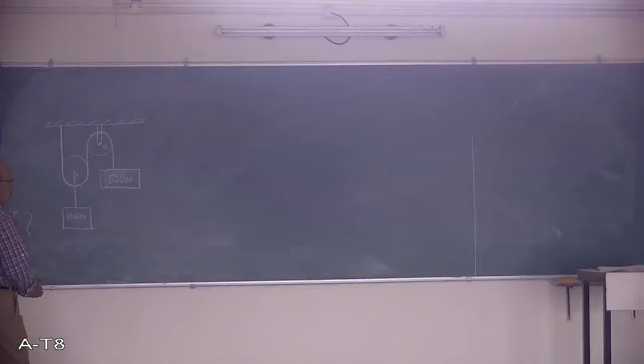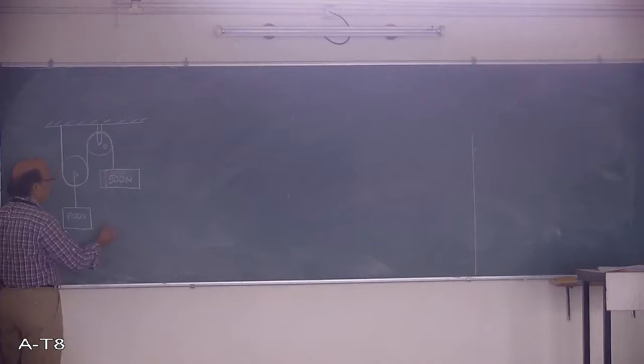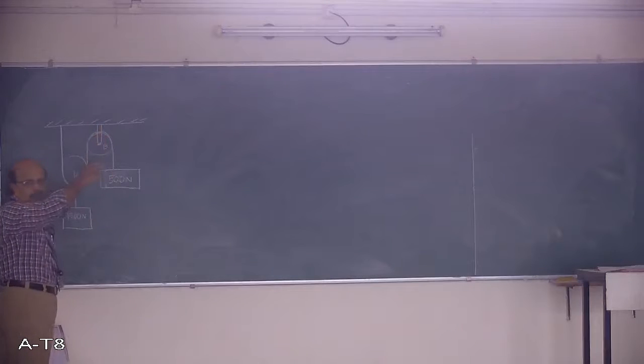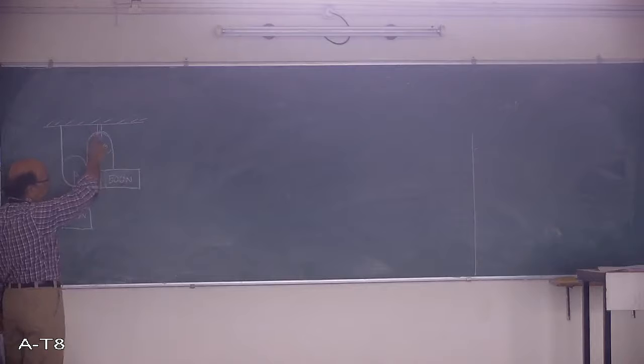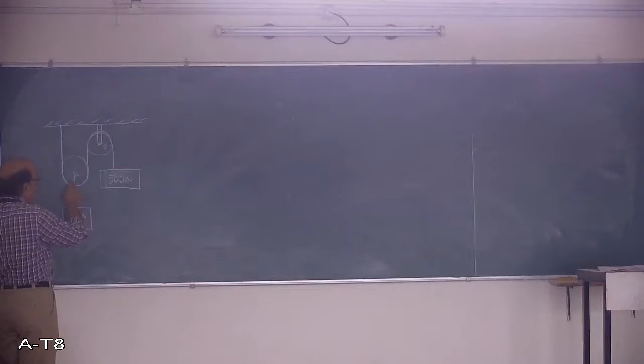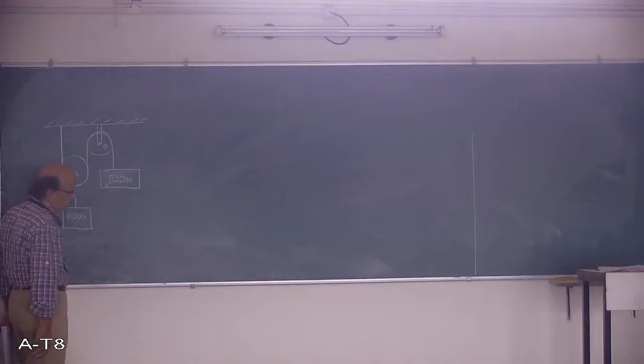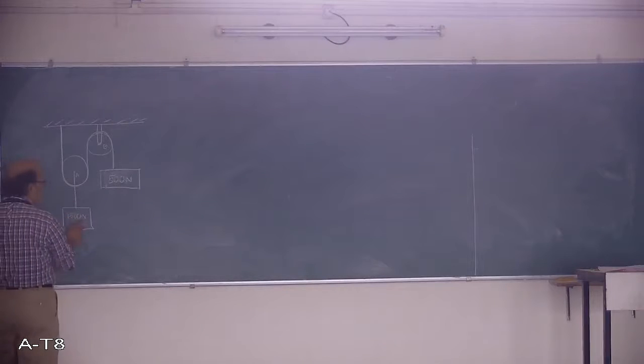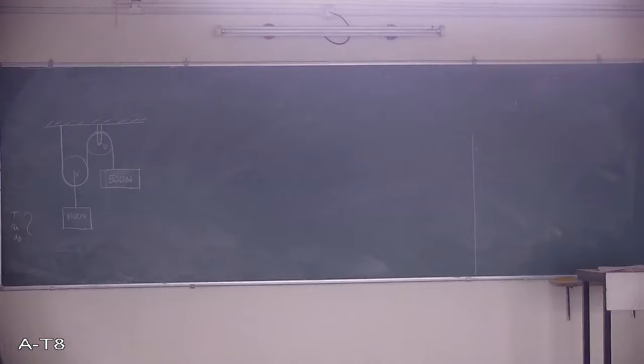Now you can just apply your logic. Now if you leave it, what happens? It starts moving up. Now when it moves down, it has got the rope all round. So if this moves by a distance x, this will move by a distance double of that, because only one string has to move. Here half the string will be taken, half will be wound this side. So the velocity of this one is double of this one, and acceleration also automatically double.